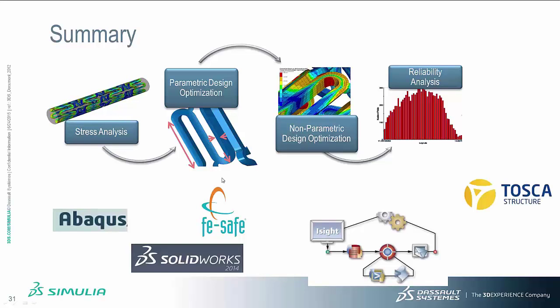Here we have shown multiple tools that we have used. We used Abaqus for the stress analysis calculations, FE-SAFE for the fatigue factor calculations, SolidWorks for creating the geometry, Isight for doing the parametric optimization as well as non-parametric optimization and automating those components, and we used Tosca for the structural optimization in the non-parametric design optimization space.